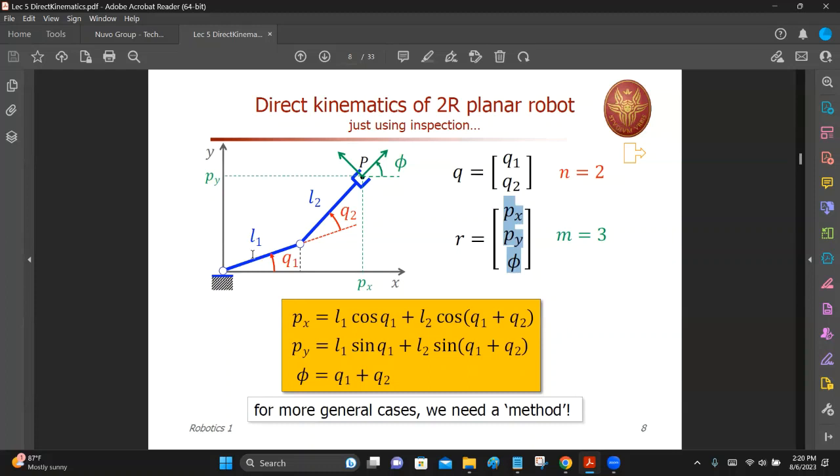That is how joint 1 also got this Q1, because it's coming from its reference. The reference for joint 1 is actually frame 0. Frame 0 means this frame. This is the horizontal axis. The link 1 angle is measured from the horizontal axis to the link, and the link 2 angle is measured from link 1 to link 2. So that is why you always get this Q1 and Q2.